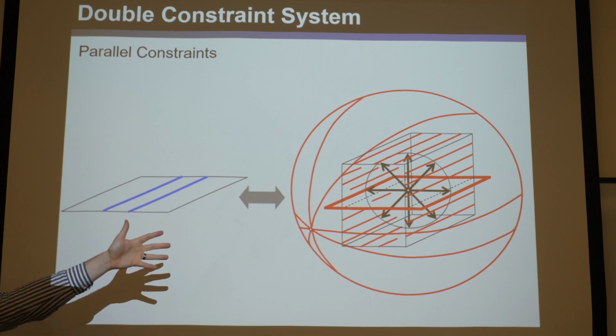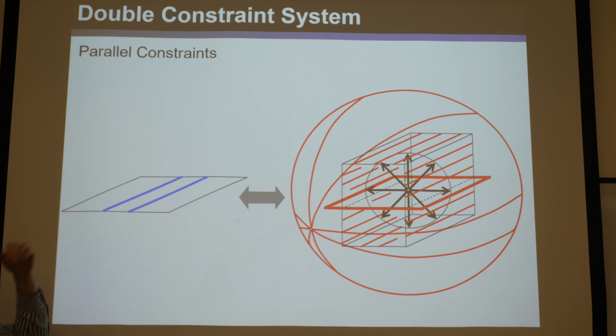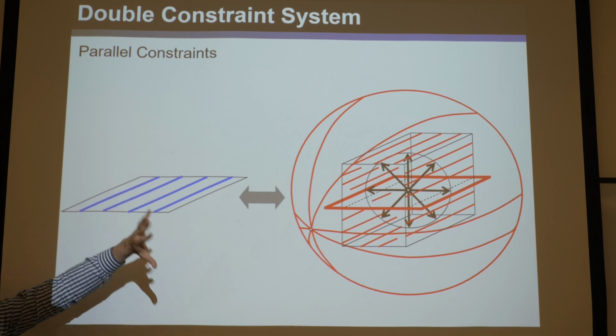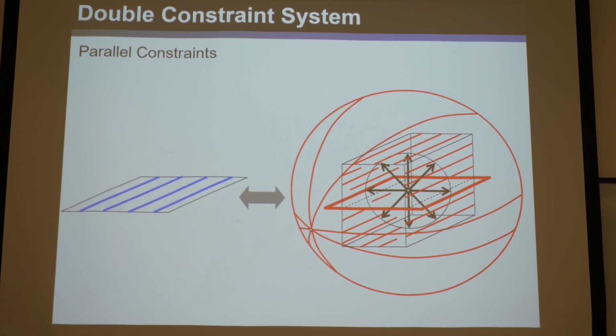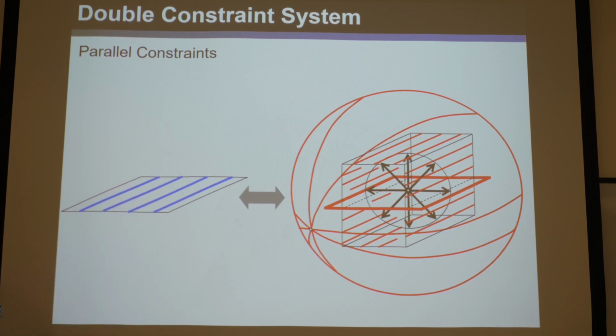And remember, we found all the red lines that intersect them. Now let's see if there's more blue lines that intersect all those than just the two we found. And you'll find, there's infinite blue lines more, and they all lie on this infinitely large plane, and they're all parallel. So you can find, there's no other blue line outside that plane or anywhere else that satisfies the rule of complement patterns for this freedom space. So this is the constraint space. And here's the whole point, is...